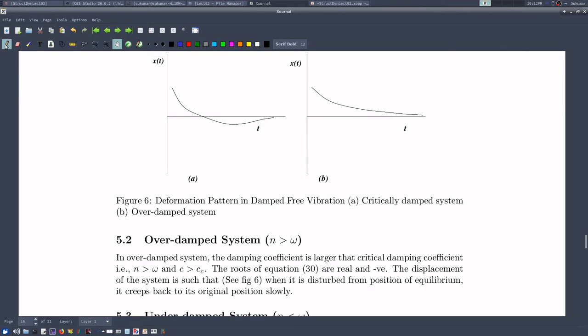And we have already seen that the critical damping coefficient of the system is a system property, which is Cc equal to 2 root over Km. I'm just repeating for the sake of remembering, which is equal to 2 m omega n, which is equal to 2 k by omega. So all these three expressions I can use for Cc depending on the known value of the system.